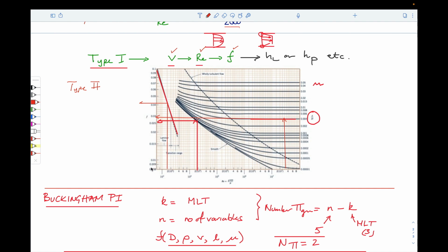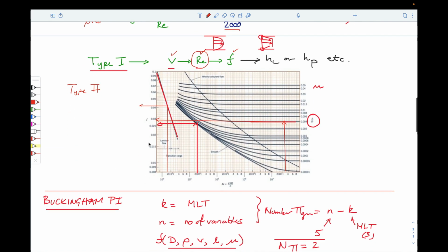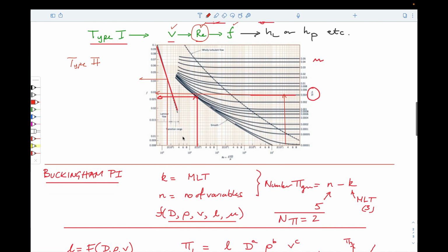So in those conditions, we typically have to make a guess of a velocity, use that velocity to calculate a Reynolds number, check the Reynolds number to get the friction factor, calculate what the velocity is from the friction factor, and then recheck the value of Reynolds number to make sure that we're relatively close to it. And so we have to iterate towards a solution in that particular case. So that's the energy equation in pipe flow, which is utilizing energy losses.